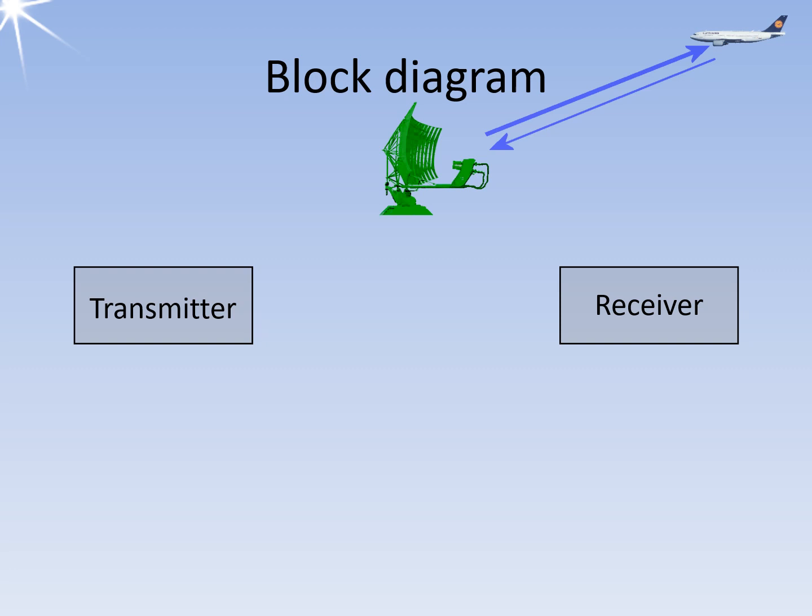The criterion for the designation monostatic is that the calculation of the target distance can be made in the same way as is typical for monostatic radars. That is, the outward and return paths are of equal length and the one-way distance to the reflector can be calculated from the delay time by halving it.